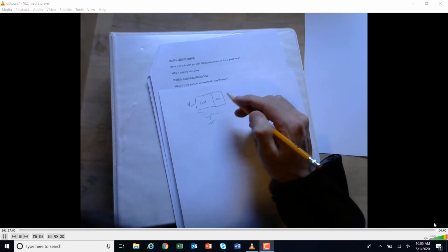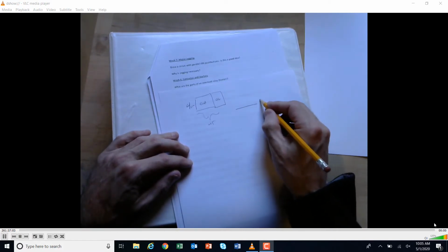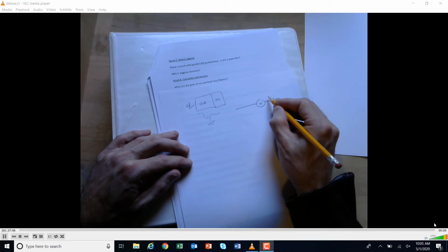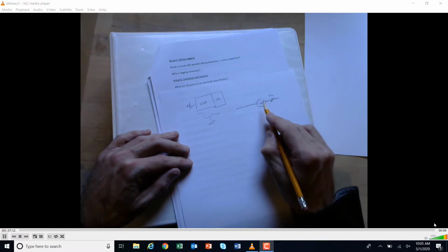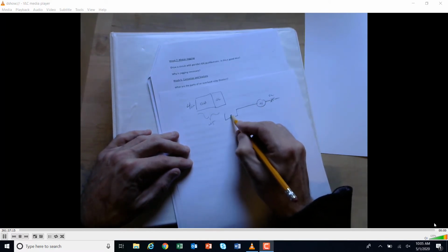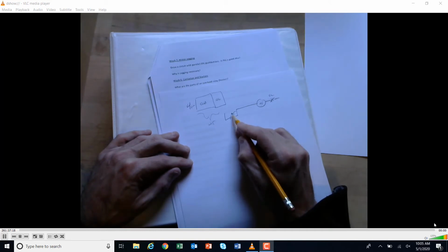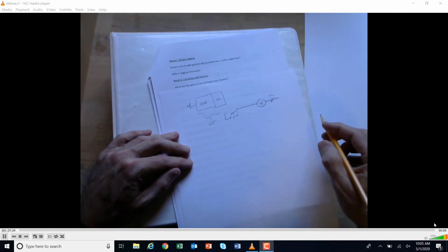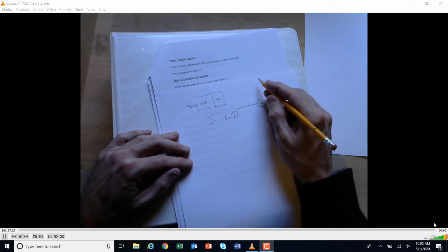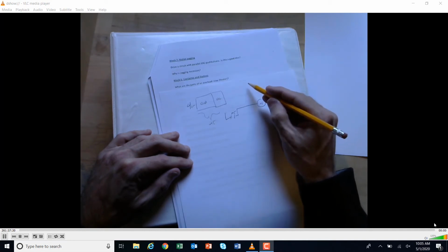So the whole operation of overloads and how they worked, and how when we built control circuits and we put the motor starter and then we put the overloads here, the purpose of that was to bring down the motor starter. And when the motor starter comes down, the memory comes down on the control circuit. So that goes off, okay? And that way it won't automatically restart. And then this overload, because this went down, the main contacts went down, right? But the overload was part of the power circuit. It had the heaters up here. And when they heated up, that's what caused that to open.